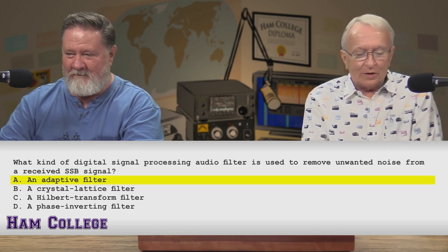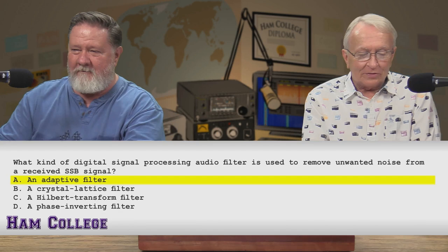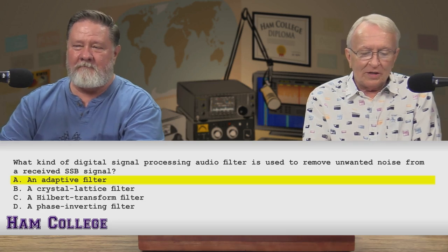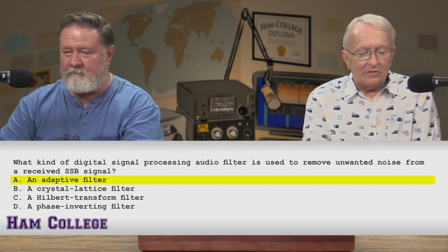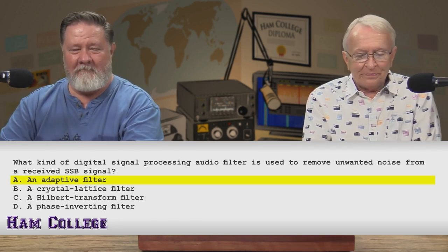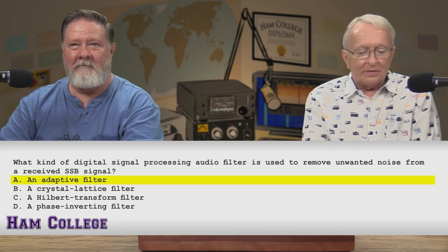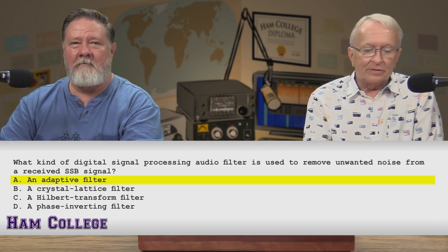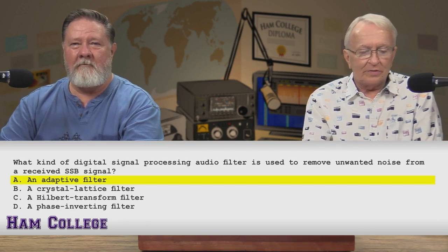Adaptive filters are required for some applications because some parameters of the desired signal processing operation, for instance, the locations of reflective surfaces in a reverberant space, are not known in advance or they're changing. The closed-loop adaptive filter uses feedback in the form of an error signal to refine its transfer function.